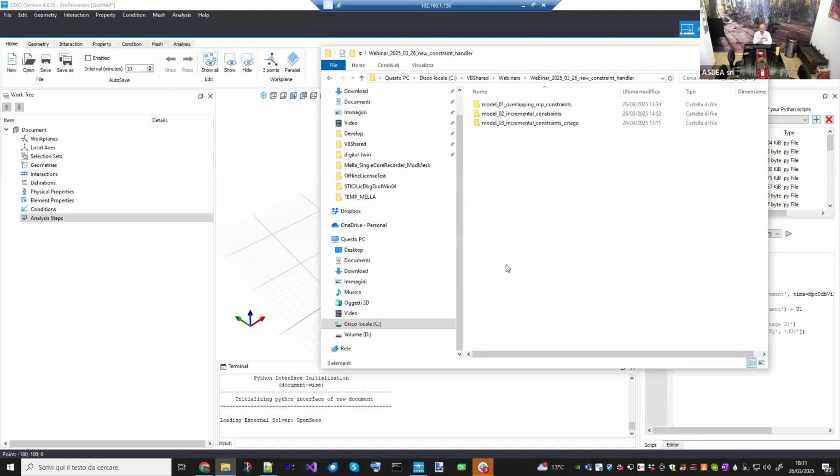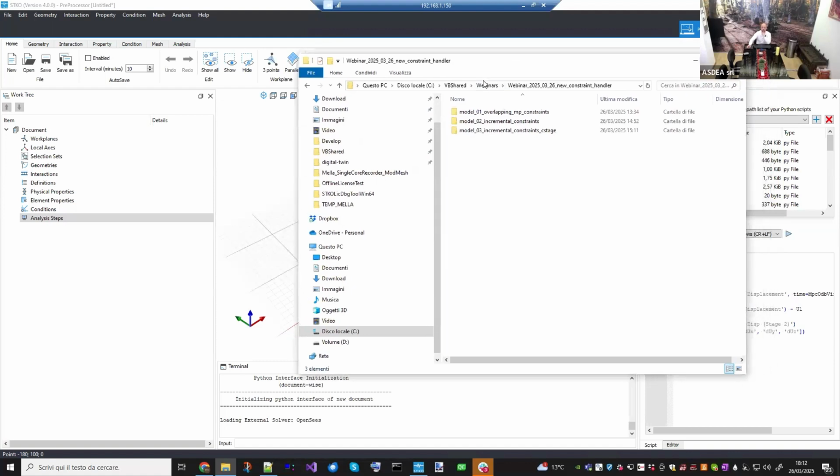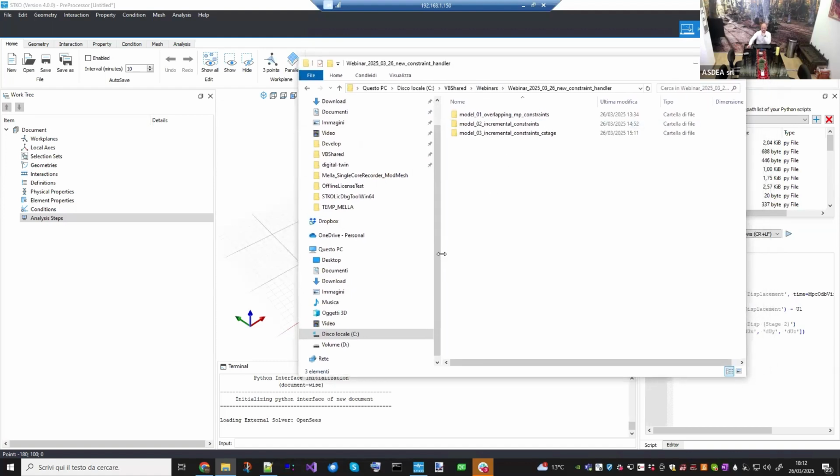treat constraints incrementally. So basically, a constraint imposes exactly a constraint on the displacement. And if a constraint is applied not only at the beginning, but on a later stage of the analysis, now in the current version of OpenSees, this constraint will apply the constraint incrementally, so only on the incremental part of the solution. And this actually allows us to do many things, for example, construction stage analysis.